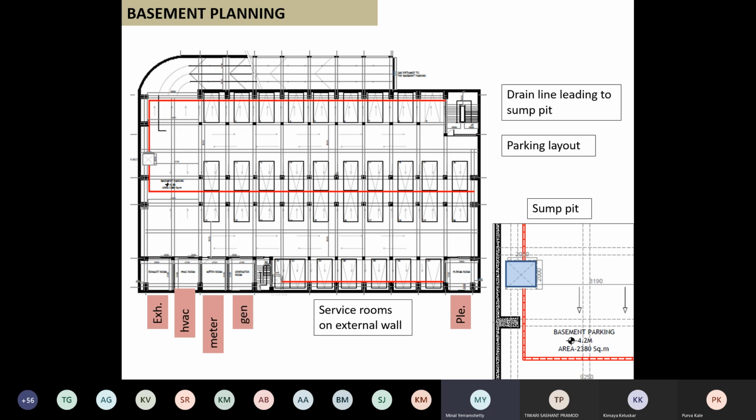Parking layout has to be shown, and again you have to find out what are the kind of requirements for your site. You need to attach to the bylaws, find out the number of parking and then plan for it. And if you need to go for a larger basement, you will have to plan for it. And that's the reason why you will see that sometimes basements go as deep as 3 floors, because the parking requirement is there. And when you go down 3 floors, people generally don't use ramps, they would go for car jacks, or you hoist the car up and down, or car lifts are there. Or you have double parking. All these kind of new technology has come up because parking has become now a very overriding factor in planning.